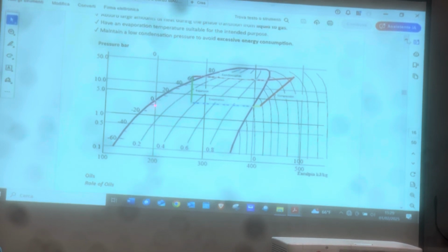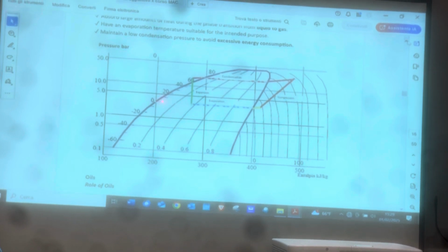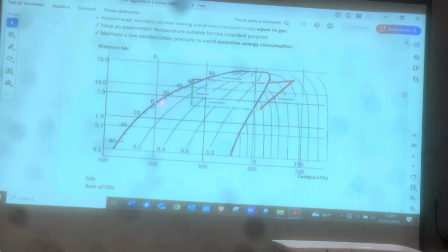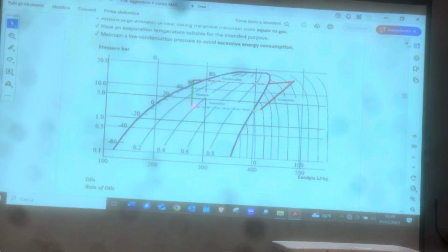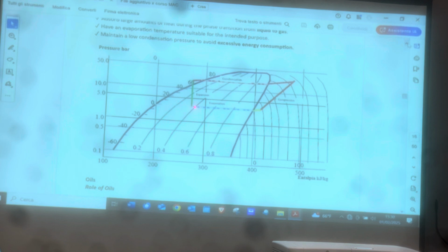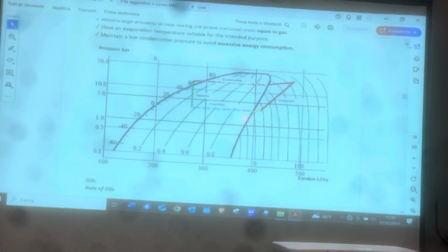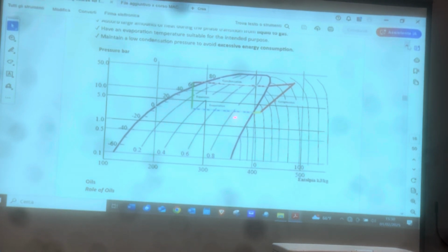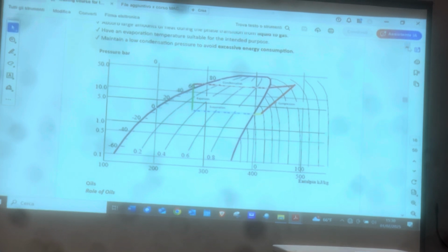So if we start with the right hand side, you've got 100% vapor line, then I've got the saturation line, and in here I've got 99% liquid content, 1% vapor, and as we move and the evaporation process completes, I will have at the end, before the saturation line, 99% vapor and 1% liquid, yeah? And that's going to illustrate the outlet of your evaporator. Once it goes over the saturation line, I'm in 100% vapor.